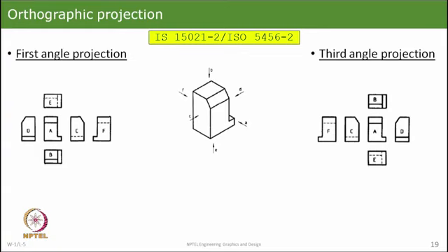Another way is the symbol that we use on drawings, which shows how you view the frustum of a cone, and the pictures of that are shown here. In first angle projection, we put these two pictures together. There are two views. This view comes from looking at it from the front direction, so this circle shows completely, and the back circle also shows completely. So, two circles.